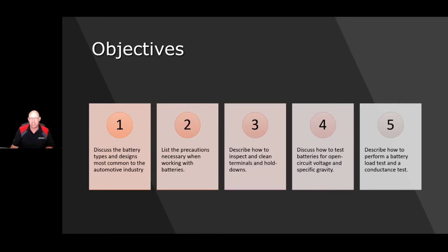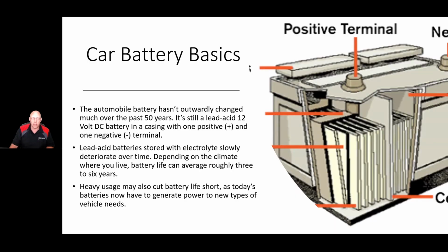So load testing is a massive saturation of the battery and a massive load on it. A conductance test is a light load, looking at recovery rates and the ability for the battery to recover and replenish itself. Okay. All right, moving on.